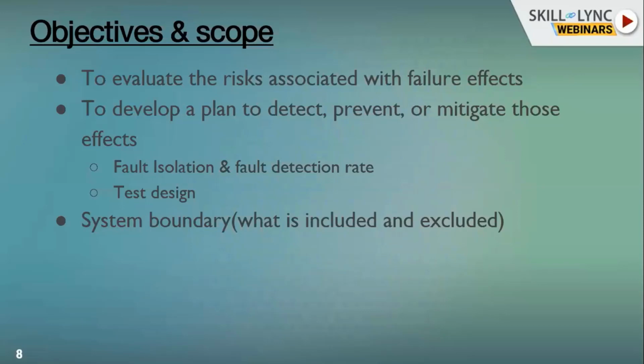And this is very important in the aircraft industry, where they define which components need to be changed within 200 hours or 100 hours. And then something else comes in, reliability centered maintenance. All those other things come into the picture. They use the FMEA as an input to develop their long-term maintenance schedules for a product.